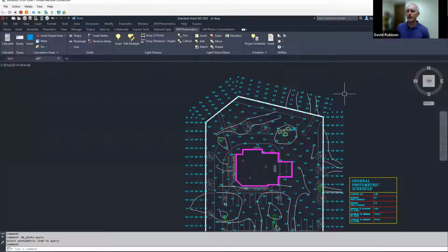When you rotate the grid, can you also rotate the foot candle values? No, you can't rotate the foot candle values. We are always going to do it, the foot candles, at 0 in AutoCAD. I realize that civil engineers, sometimes you guys, you twist your drawings around. And Design Master doesn't like that, unfortunately.